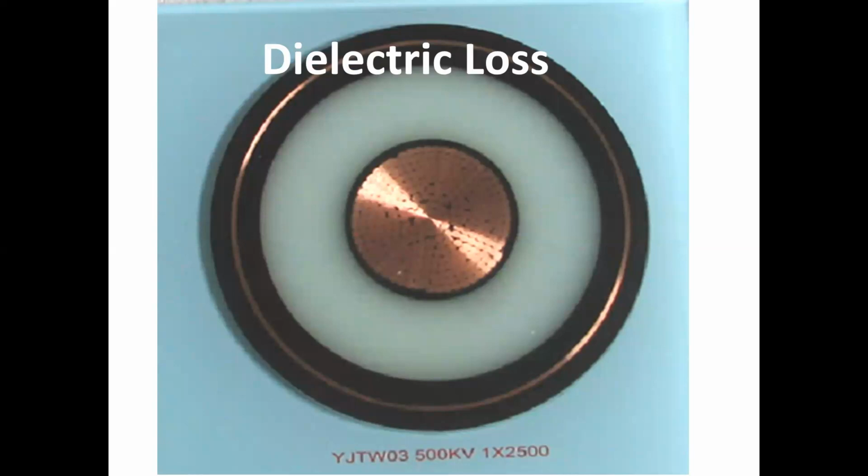Dielectric losses have to do with the stress that an alternating current has on the insulation. The electrons are forming in or aligning in one direction, then the next very rapidly. And what that does is it leads to stresses on the insulation of the conductor. And this is much more apparent on higher voltage installations. But that stress causes heat loss. And whenever we have heat loss, that means a loss of power and watts. So this leads to a little bit of lessening of the efficiency of the system.